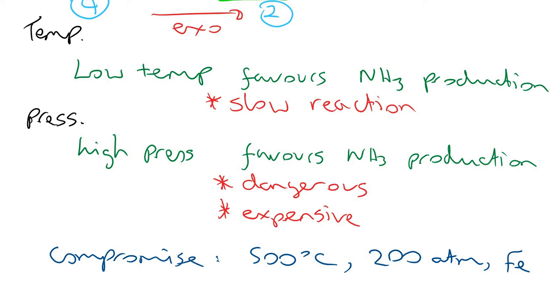So with this reaction, as they're all gases that are used, what happens is the gases enter the reacting vessel, ammonia gets produced under the conditions, but when you cool down the gases, ammonia will reach a liquid stage first because it's got the highest boiling point. So the ammonia is just tapped off as a liquid then, and the other gases are literally just circulated back throughout the system, and it goes in a continuous loop.